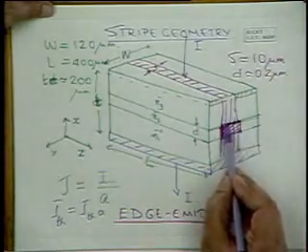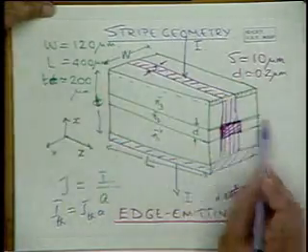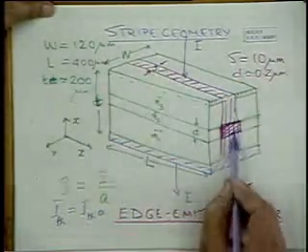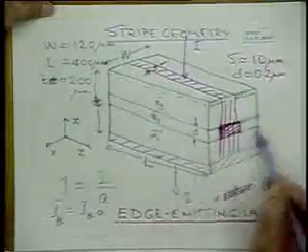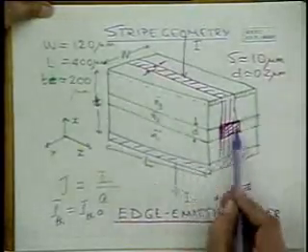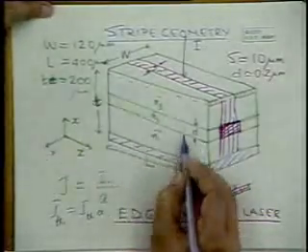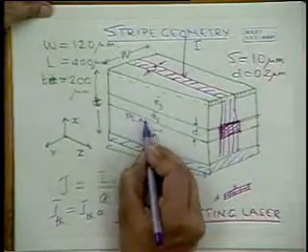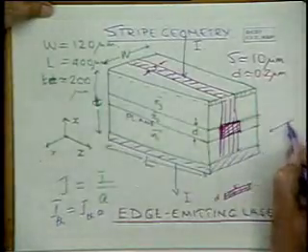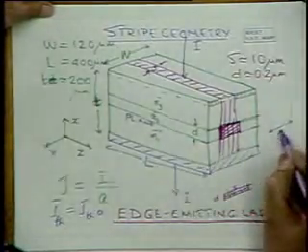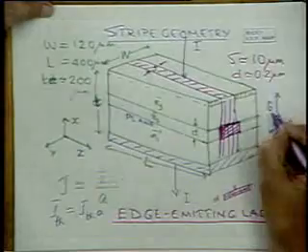We are interested in the light output coming out from this laser. The light output will obviously be coming from this aperture. And what is the modal pattern? The light output will spread both in this direction as well as in this direction, both in X and Y direction. So what is the theta? One of the definitions is, this is the plane of the active layer. In this plane we define the divergence as theta parallel, and perpendicular to the plane, this is theta perpendicular.